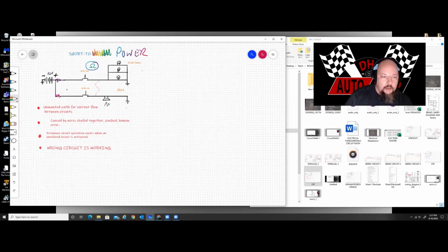So what I will do is, again, I have my fuses out. These switches are open, okay? And just to cover all the bases, I would go here and then here and see if I have a connection. Okay, right there. And in this scenario, I would read OL, out of limits, open. Some meters will give you the number 1 on the far left.